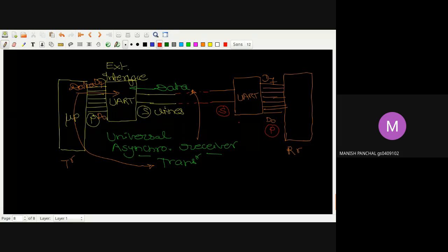तो पहली ड्यूटी ये हो गई. दूसरी बिट ये हो गई कि यहाँ पर जो मार्क, स्पेस, स्टार्ट और स्टॉप बिट हो गए, ऑब्वियसली ये यूआरटी तक ही सुटेबल है, क्योंकि यहाँ पर तो मेरे को D0 to D7 मेरे को सिर्फ डाटा से मतलब है. So in the case of this, उनको सबको रिमूव करने का जो फंक्शन है वो भी ये यूआरटी करेगा.